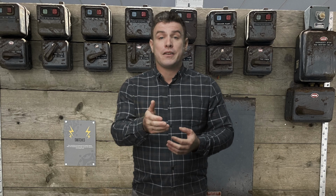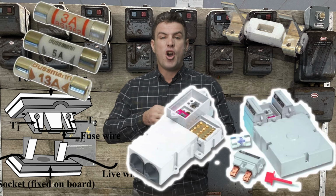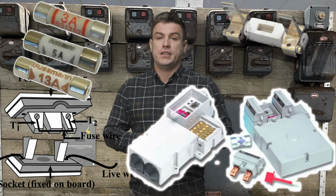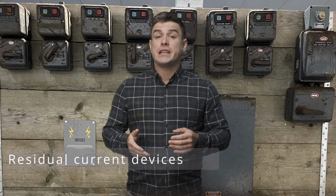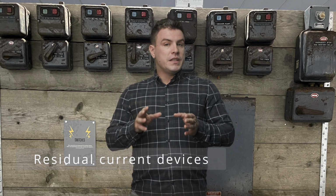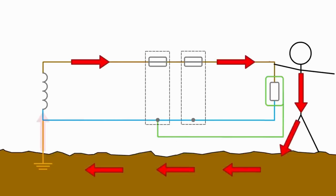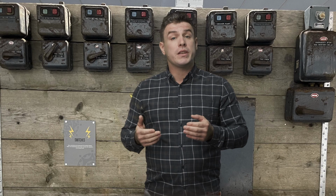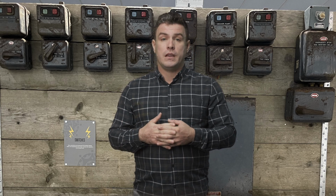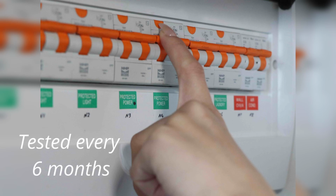In addition to mechanical breakers, there's a number of different fuses which are designed to break a wire by overheating it in the event of an overcurrent situation. Each one has its own BS standards. RCDs were mentioned, and I do wonder if this is one of the best things that's happened to the world of electrics in the last 50 years or so. They monitor the line and neutral and look for imbalances by creating a magnetic field which pulls a trip coil when a current is passed through an earth. As there's a mechanical element, they have a test switch which needs to be tested every 6 months.